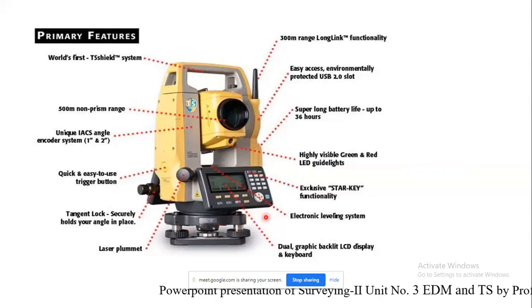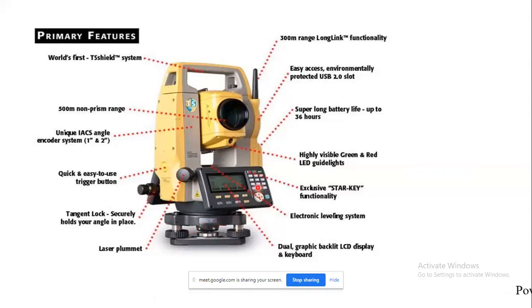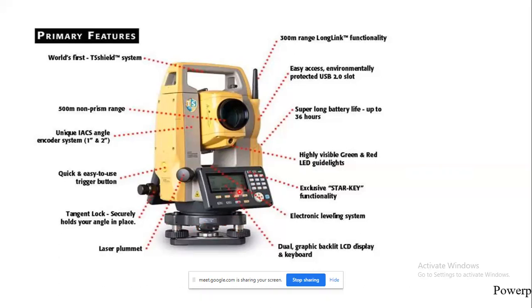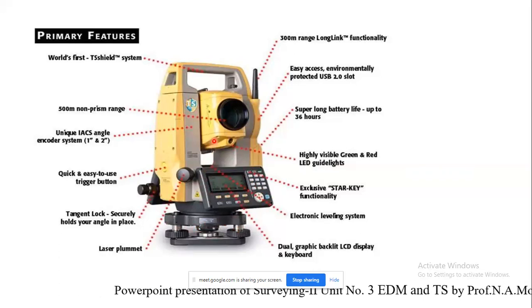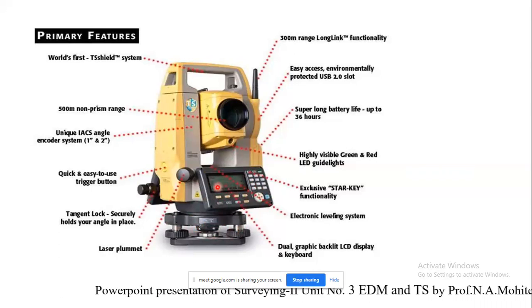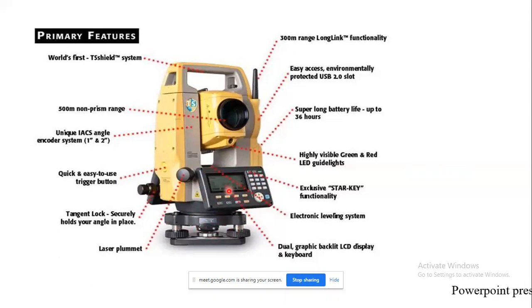Whatever work you are going to do, that of the leveling, is displayed over the tripod stand. We are going to see that during the practical session also. When you keep the bubble tube or telescope parallel to two foot screws and move the two foot screws inside and outside, the bubble seen here digitally moves to the left and right side. These are the same deviations which you see in the dumpy level practical.